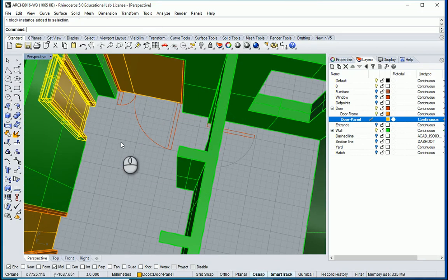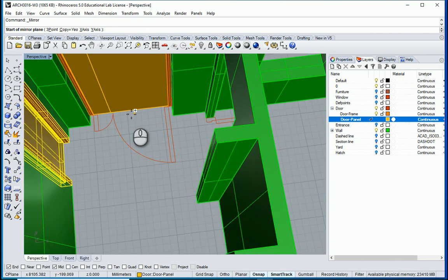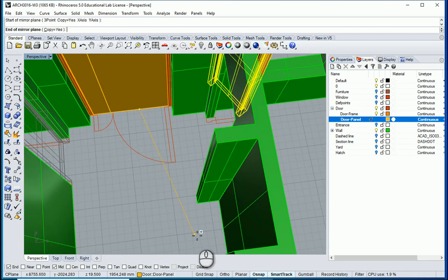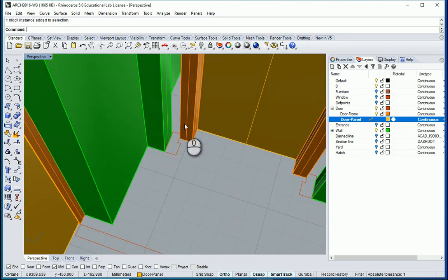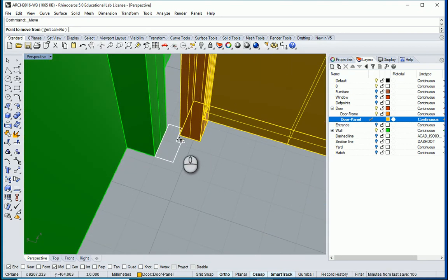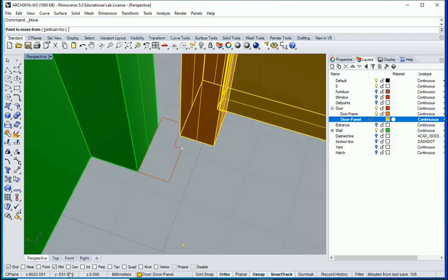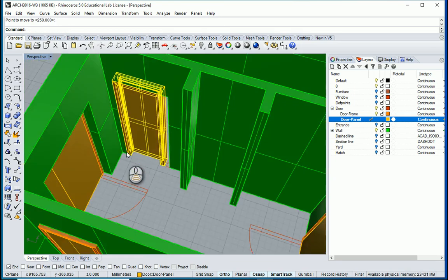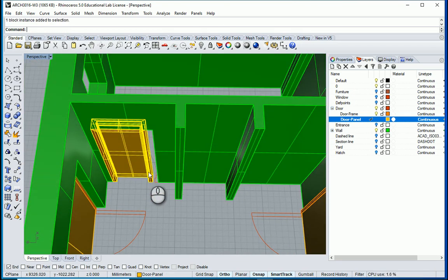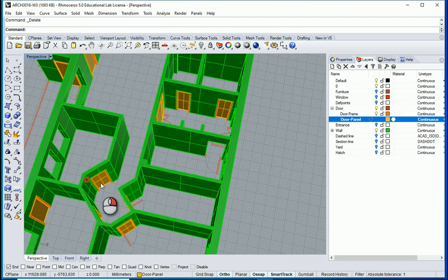So I wanna go with MI. I wanna mirror this door, use ortho, and I want to just use move to locate it in the exact place. Oh, this seems one of the bigger doors, so how about I orient this other one?